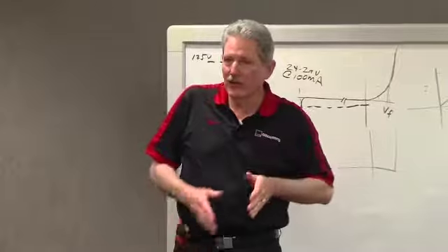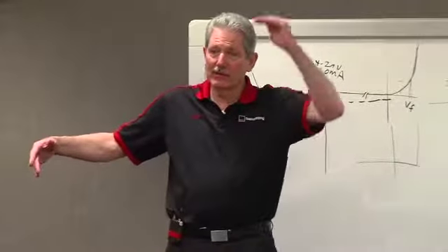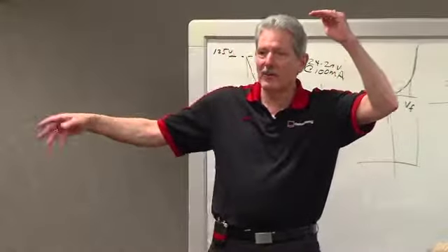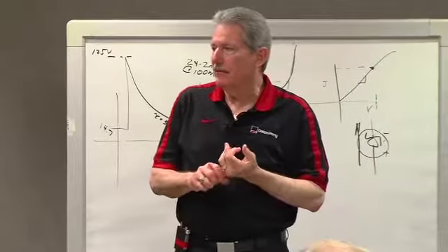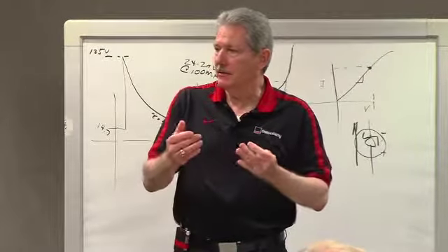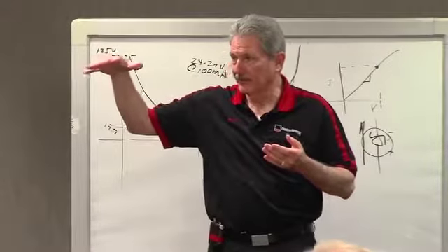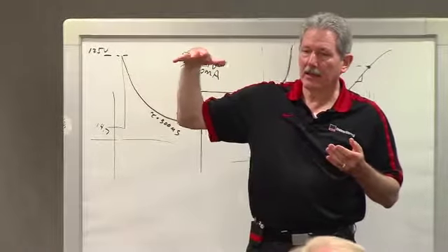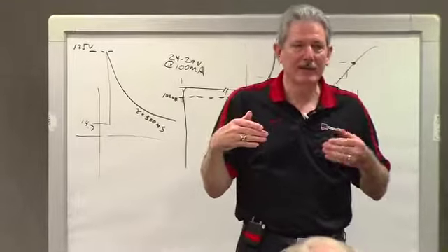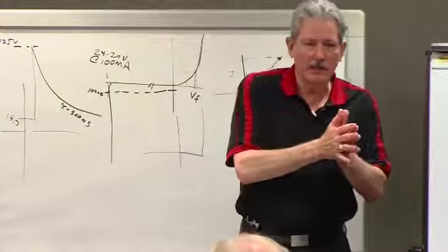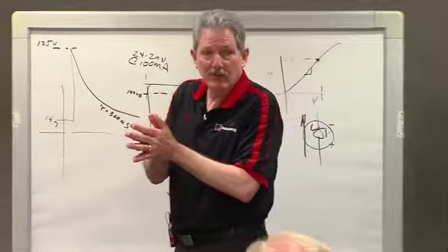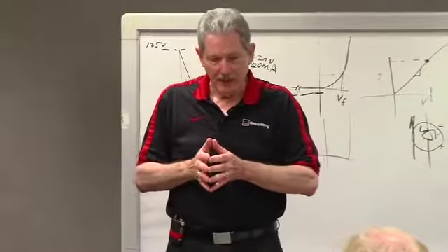If the voltage is too low, it takes too long. If the voltage is too high, you damage the battery. So one of the functions of the regulator is to regulate the voltage. Another is, if there is a fault, to indicate that fault. We want to tell the driver that you have a problem so that you can get service.